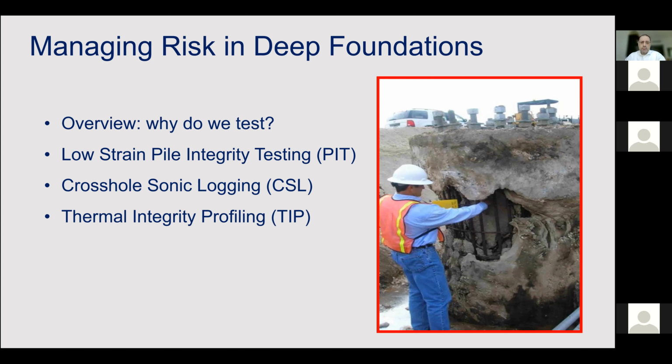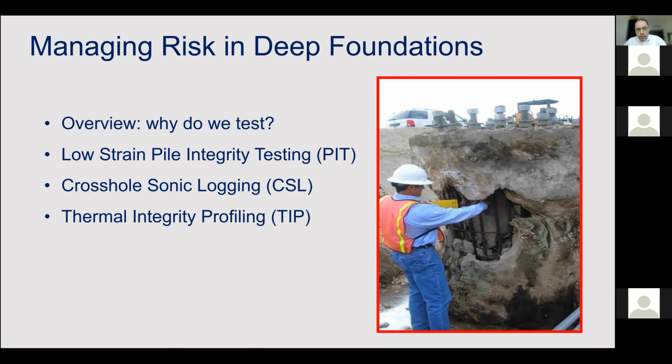There are several methods available in the market that enable us to ascertain the quality of the installed deep foundations, mainly the widely used low strain integrity testing, the cross-hole sonic logging, and the testing method on which the concentration of the talk today will be, the thermal integrity profiling.